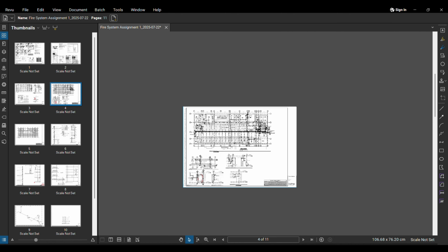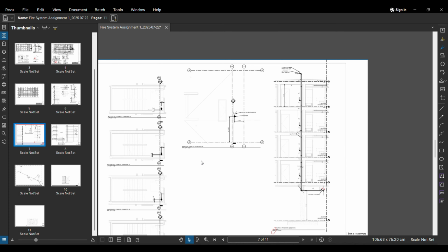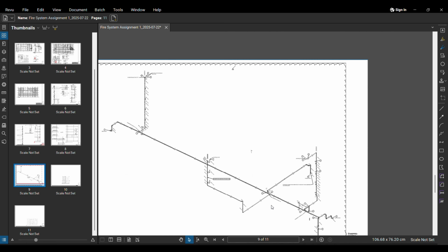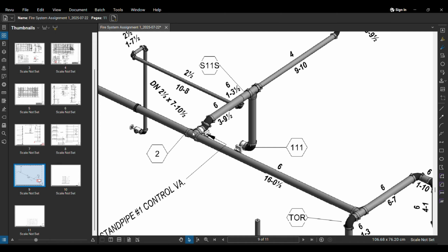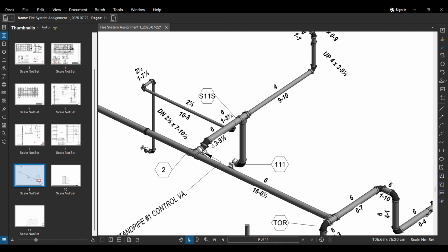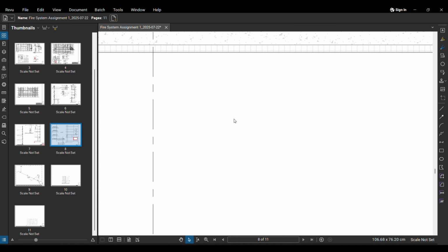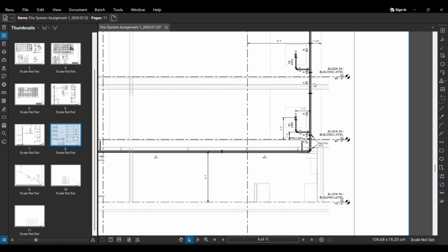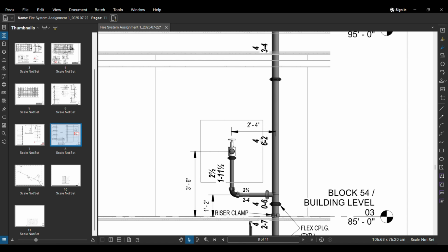So what is left? I think you guys have to model this rack here. I think it is not too difficult to model. You can use this isometric view to model this. You have to take a sort of stub up here, use all the sections to get the middle elevations, lower elevations here, and then I think we have some separate plans for these stand-up pipes here as well. Here you can see the stand-up pipes. Here you can take this equipment here, and then the length of these pipes.